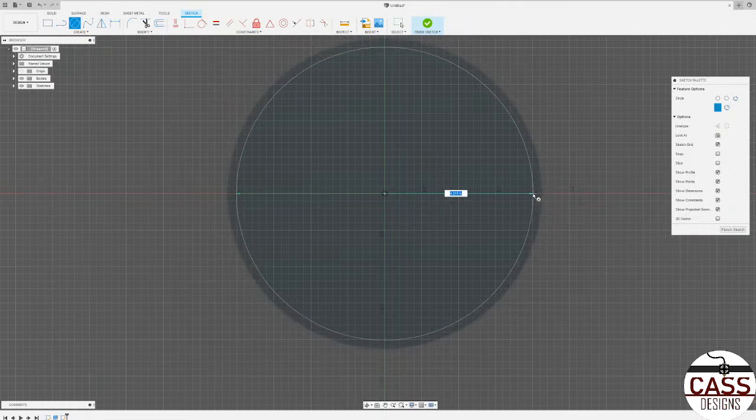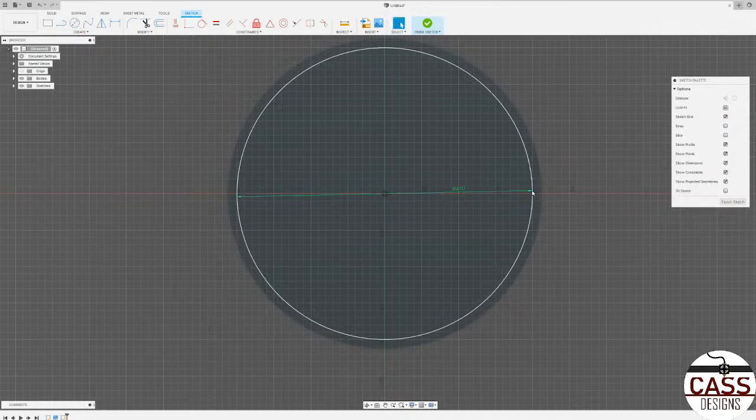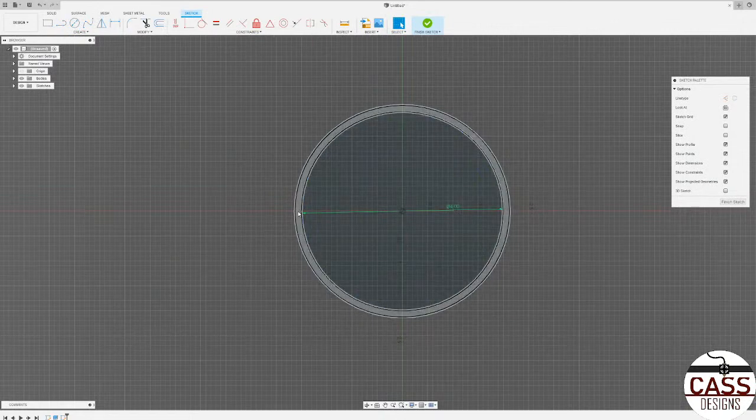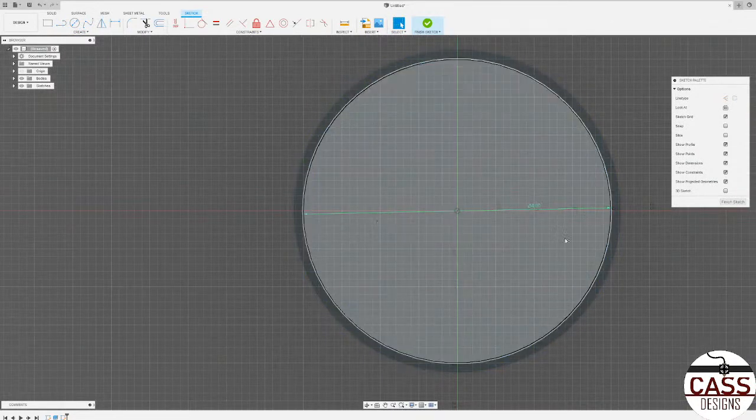So to create kind of a 1/4 inch on the inside here, well, I'll say 1/8 of an inch because we want to make sure that the cup fits. You subtract a 1/4 inch from this outer diameter and you make it just 4 inches. So you click 4, click enter, and boom. Now we got another circle, a smaller circle on the inside here.